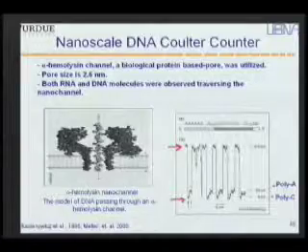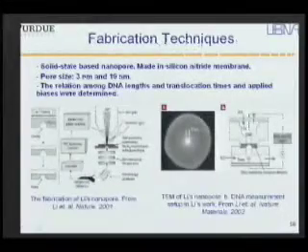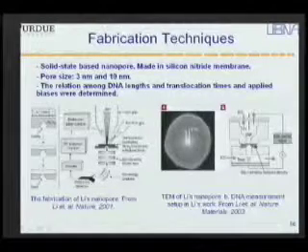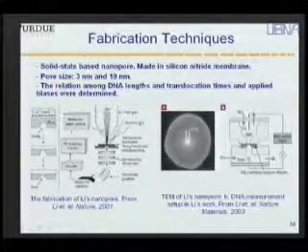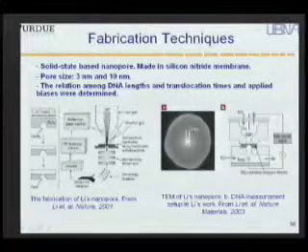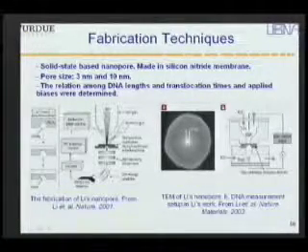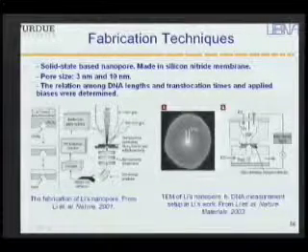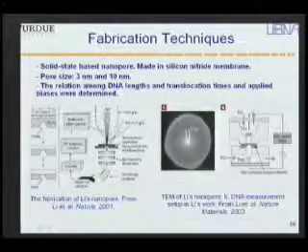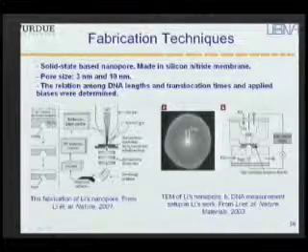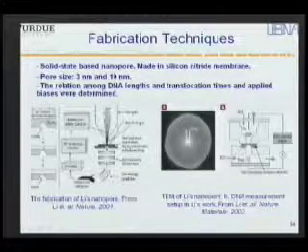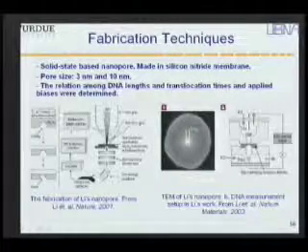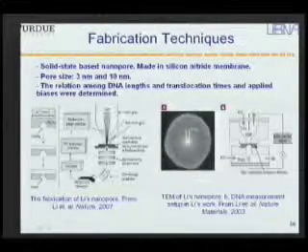So for this type of sensor, there have been different approaches to make it. I'll just quickly review this here, but the references are in the notes, and you're welcome to go and look at them in more detail. One approach, on the left here, is in a silicon nitride membrane using an argon beam, where you continue to etch this surface with a little cavity, and as soon as a pore is exposed, the current through the pore increases, and hence you can stop the etching. That way people have made these thin nanopores in silicon nitride membranes.